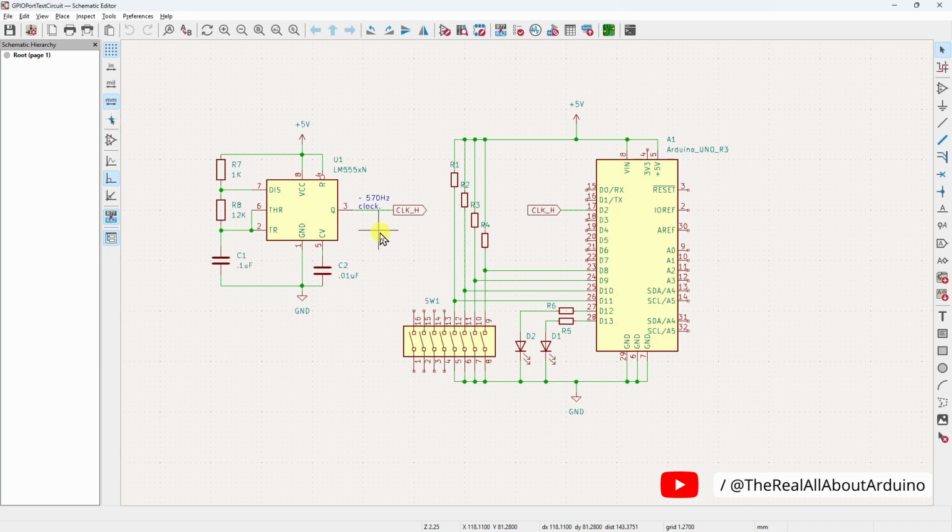But the main reason for doing it this way is because, as I said, it is easy for you to set up. The coding is very simple. You don't need to muck around with CPU registers to set up a timer interrupt. And also there's less risk of a conflict. If you're using something that uses a timer, and I showed you a particular timer, then it'd be much harder for you to adapt. So using this method is sort of an easy way of doing it. And then when you're finished, you can just tie this to ground if you didn't even want to change your code, or just comment out the attach interrupt and it'll be effectively disabled.